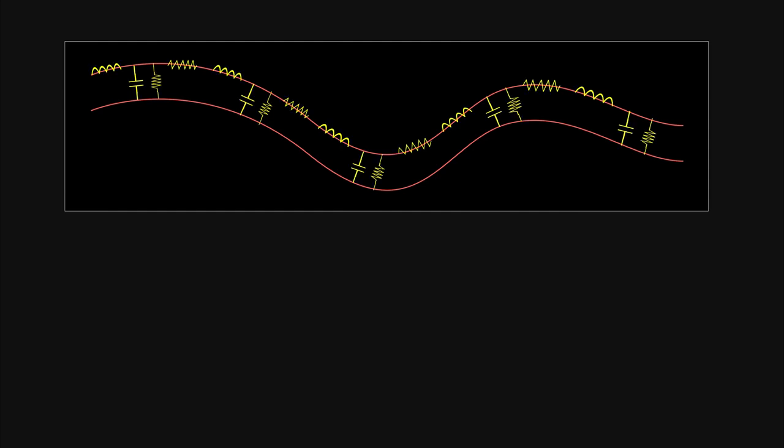In part 1, we saw that the transmission line is nothing more than a series inductance and resistance and shunt capacitance and conductance distributed along the wire. Assuming the wires being perfect conductors separated by perfect dielectric, then the series resistance and the shunt conductance can be ignored from the model. We can't consider it as a single inductor and capacitor, because the line is very large compared to the wavelength of the signal.